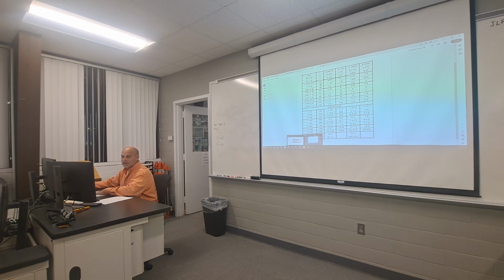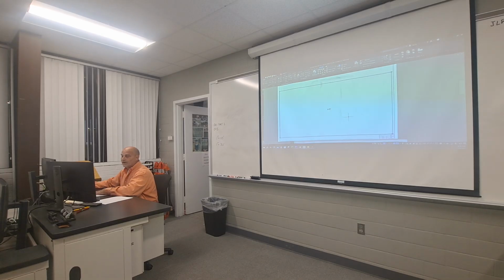Here's how you add those scales into your AutoCAD drawing. The first thing we have to do to be able to see our scales down here on our status bar is access that viewport. Remember, we're not scaling this border, we're scaling that viewport and the items that show up inside it. To see those pop up on my status bar, I've either got to single click on that viewport or double click inside to open it up. That's for those of you that are going to ask me in a little while, "Mr. P, I don't see my scales, I can't set them on this drawing." I'm going to say, contact Stuart and ask for video.